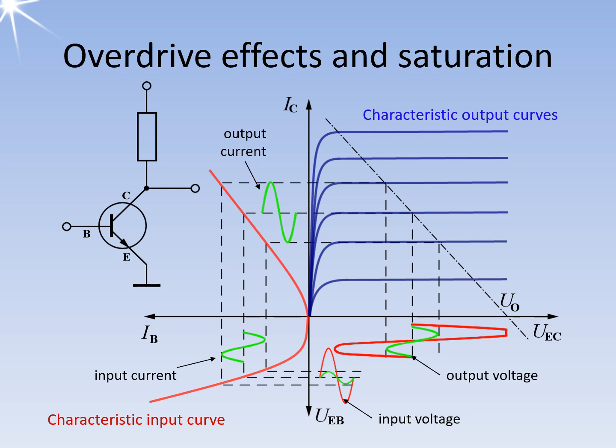The figure shows the characteristic curve of a transistor amplifier in a grounded emitter transistor circuit. Ideally, the input signal should be in the linear part of the input characteristic curve. With a very large input voltage, shown as red sine waves, the peaks of the sine wave are in the nonlinear part of the input characteristic. As a second effect, the amplified peak would be larger than the supply voltage. This means that the peak is not only limited in the amplification but also clipped. This is the effect of saturation of a simple amplifier.